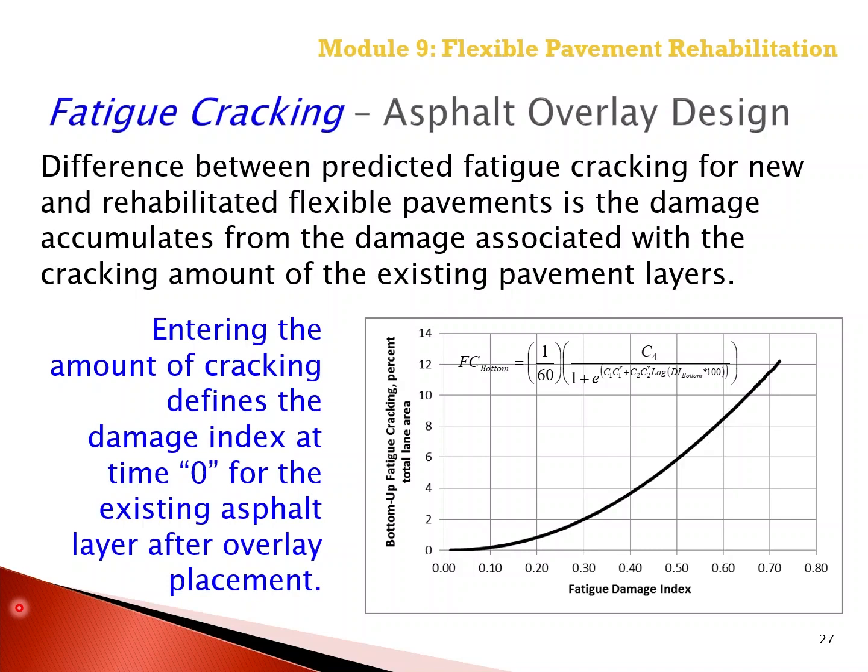In other words, the fatigue cracking transfer function to calculate the fatigue damage in the asphalt overlay and existing layers is the same. The critical response, again, is tensile strain, which is associated with the damage index in the lower layer of the existing asphalt layers, and is used to determine the starting fatigue damage index after overlay placement, as illustrated in the graph on the slide.